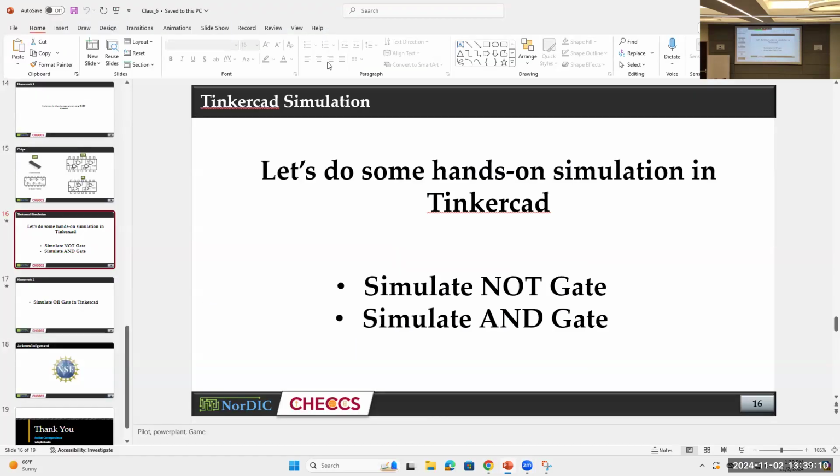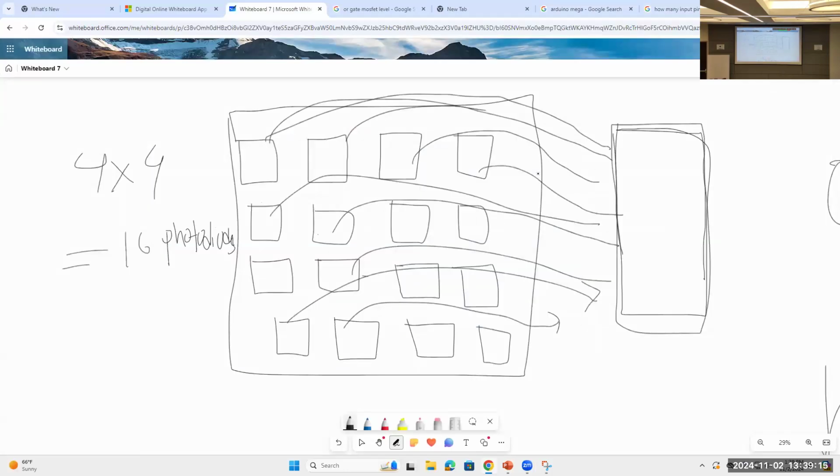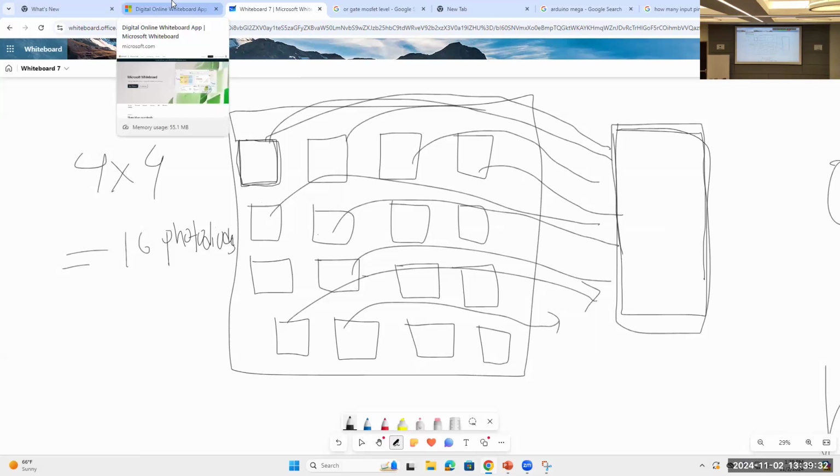And what will we do with this? We will take the input. Why are we taking analog pins? Because the sensor will be giving us analog outputs. What is analog and digital? As I told you at the very first moment of this class, digital means zeros and ones. But in this case, the photodiode will not give me 0 or 1.